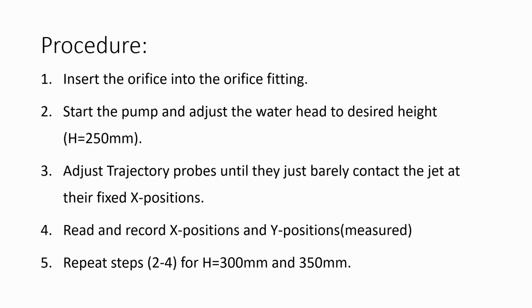Now that I have mentioned the fundamental equations and the derivations that I expected of you, we return to the procedure. Firstly, insert the orifice into the orifice fitting device, then start the pump and adjust the water head to the desired height. In the first case, the height is 250 millimeters.